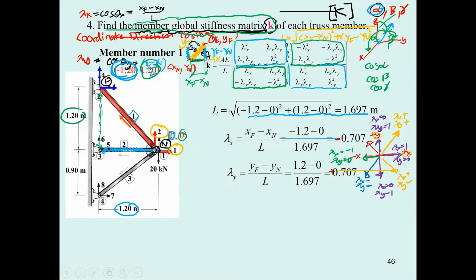When you count the degree of freedom, you count from the near end. It's going to be from the tail of this arrow, the near end, to the head of this. So it's going to be x, y, 1, 2, x, y, 3, 4. This one going to have 1, 2, 3, 4 like this. That is going to be capital Q and capital D, going to be 1, 2, 3, 4 in this order. And then you have the AE.